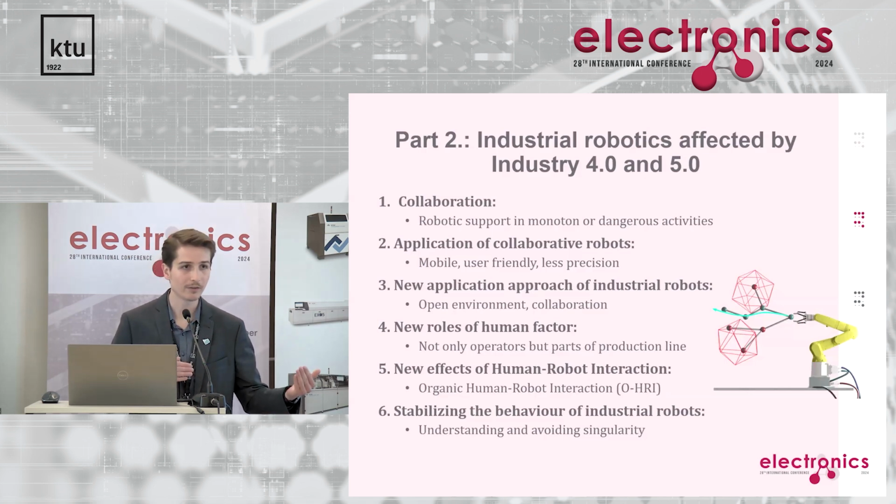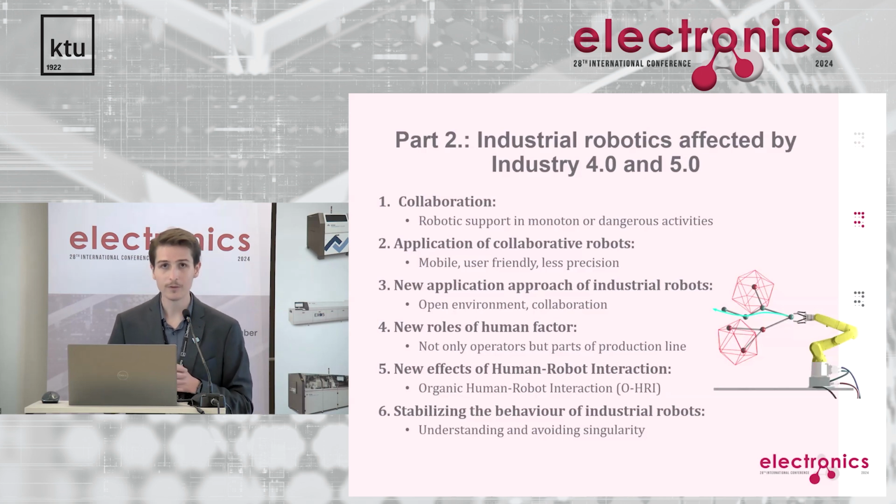and okay, we can restart the robot or we can continue the working procedure later on. However, there is a special kind of singularity which results in unexpected motion. So the robot is going through a longer trajectory, reaches a singularity point, the controller loses the control of the robot, and the robot motion becomes unpredictable. It can be harmful not just for the object, but for the humans as well. In this case, researching this direction is very important.